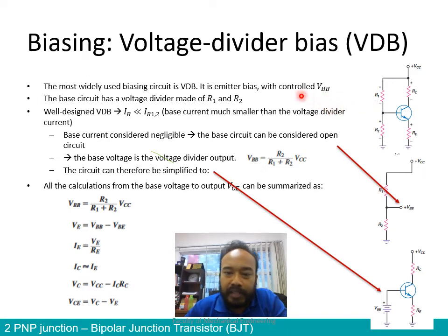So if you look at the previous circuit, we would have VBB and RE, but VBB was constant. Now, in order to change the value of the current IE, what we could do is change the value of the voltage supply VBB. So how do we change the value of VBB? It is by integrating a voltage divider. If we change, for example using a potentiometer, the ratio of the voltage divider, we would therefore change VBB inside our circuit. So let's try to analyze it.